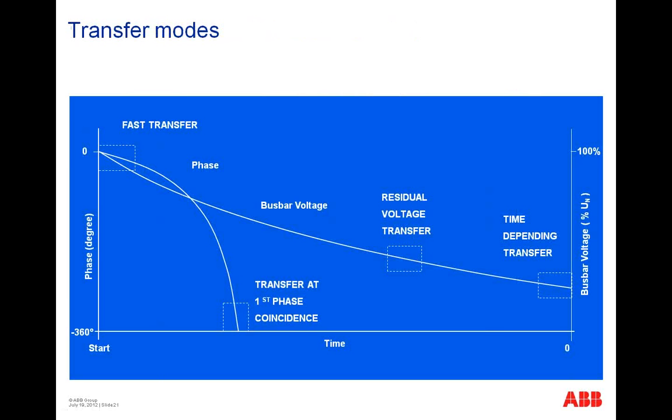I hope that up to now it's more or less everything clear. Transfer device, very fast changeover with different variants for different kinds of switchgear configurations, with 2 breakers, with 3 breakers, with 1 busbar, or 2 busbar sections with a busbar coupler. Now we step over to the more theoretical part, to the transfer modes, which make the really big difference to an ATS.